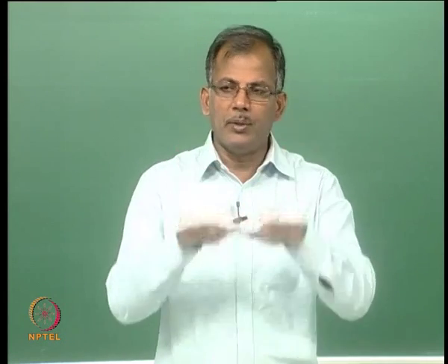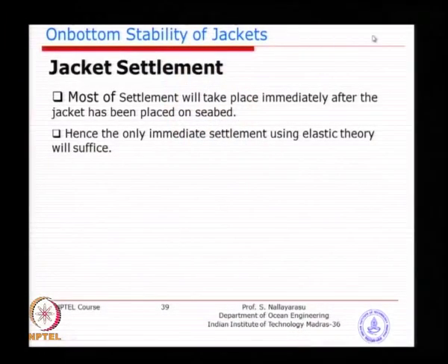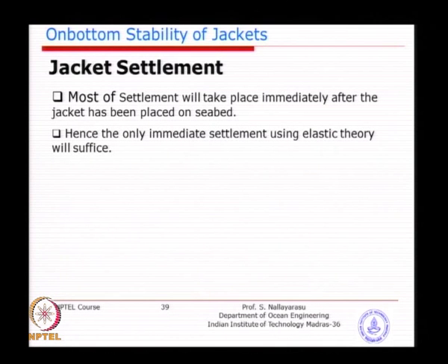If the jacket settles by too much, one of the important interfaces between the jacket and the topsides will change. So if you are not prepared for it and have not taken adequate measures to adjust that level, it will actually make the platform unusable.